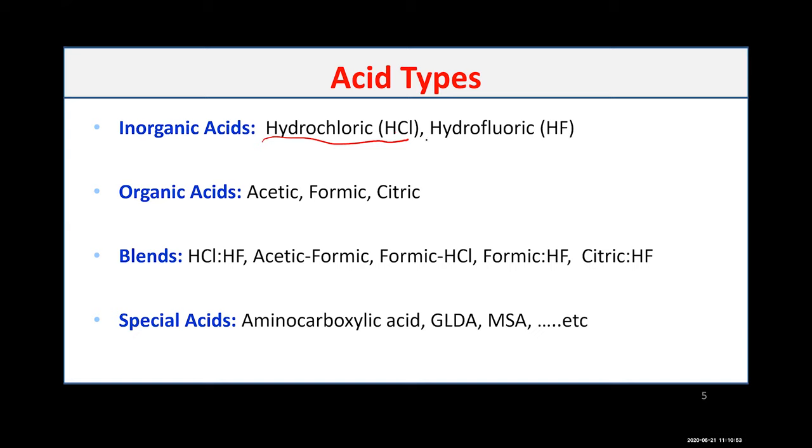The other type of inorganic acid is HF, or hydrofluoric acid, and this is the only acid that can dissolve sandstone, can dissolve silica. That's why when you hear sandstone acidizing, you should keep in mind that we are talking about hydrofluoric acid, as it's the only acid that can actually dissolve sandstone. None of the other acids in the industry can dissolve sandstone except HF. Therefore, any sandstone treatment must somehow contain HF.